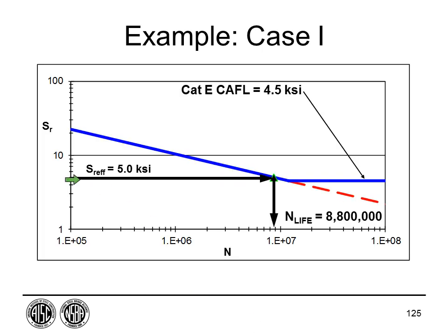How does that look on the fatigue curve? Well, I simply would come in at that stress range, intersect my curve, and if I drew a line down, I'd be at about 8.8 million cycles.